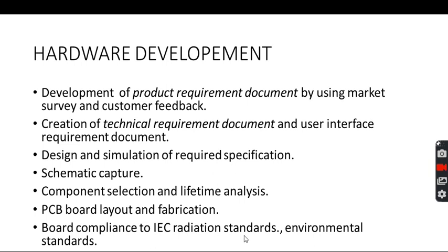And IEC radiation standards, whenever you are going for space or anything like that. During that time, radiation standards also will be useful. And there are multiple other standards. Lead free: you have to make sure that the soldering is lead free. Then CE standards are there, and EMI standards are there, that is, you should not have electromagnetic interference on the ICs. So whenever you do the hardware, these kinds of things have to be taken care of.